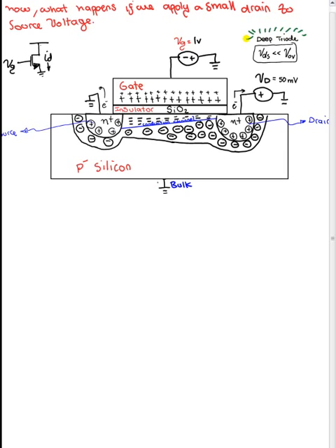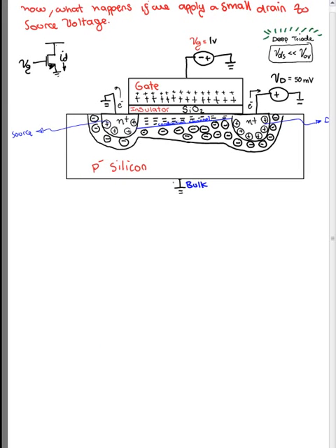So now let's note what's happening, again in a qualitative view. It looks complicated, but it'll get much better. There are 3 effects. The first one is you get a conduction channel which becomes asymmetrical. Before, when the transistor was on without a drain to source voltage, the conduction channel didn't have any slope to it. Now we get this kind of triangular conduction channel right here.